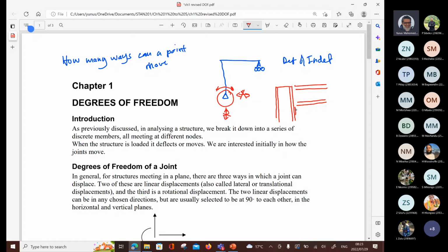So first of all, you may have a seating cleat here, and then at the end here, you need to fix that beam to the column. So one perhaps way of doing it, if you want it pinned, is to use a cleat like this. A cleat is an angle, it's just another name for it. So you put a cleat like this. Now we're looking in plan. There's the beam web. There's the other cleat at the back, which you're not seeing. Put a bolt through there and you bolt into the column. Are you with me? So that would be bolt into the column. Got it?